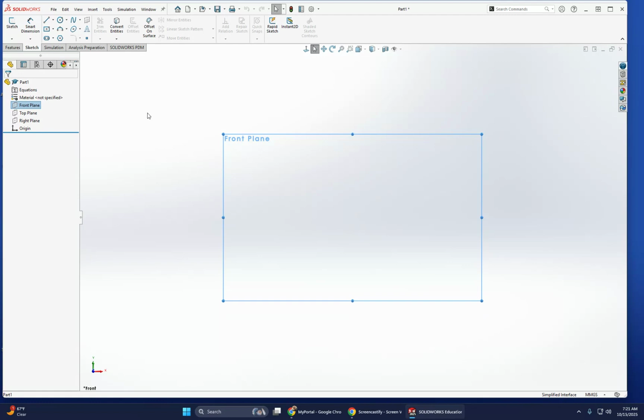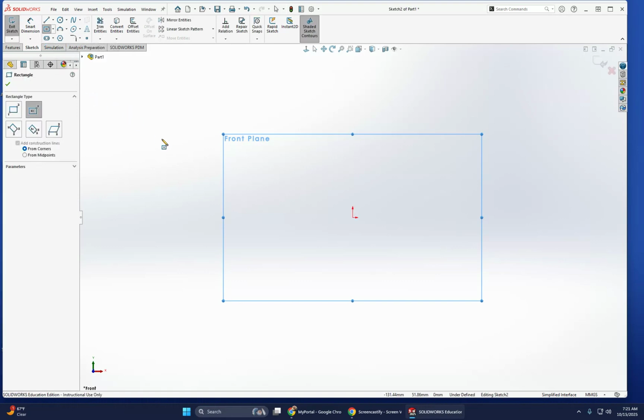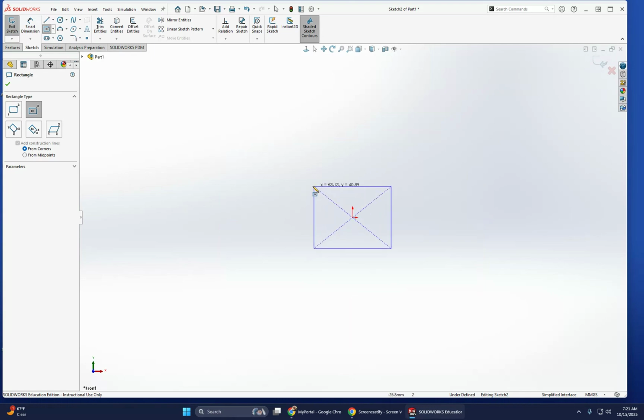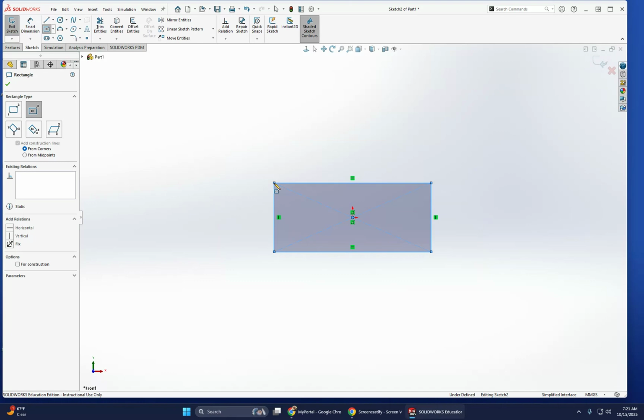So I can select any tool I want to start with. I'm going to click over here on the rectangle. There are 5 different tools. I'm going to click Center Rectangle. Why? I don't know. I thought that was a pretty good idea to start off. And you can see over here, here are some of the properties. Come over here to the origin point. Click once and then release. I can drag the rectangle out, and then I'll click again. And that's the rectangle.